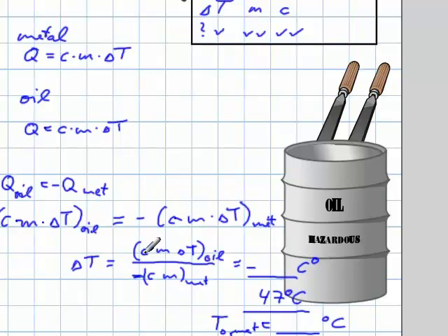This one is given in the problem as, what was that, 430 joules per kilogram Celsius degree. The mass here is 75 kilograms. The delta T here for the, oh, I'm sorry, hold on. This is for the oil here. So what I just said, 430 and 75, is down here, and then up here for the oil is 2700 and 710 kilograms, and then the delta T for the oil is 15 Celsius degrees. Everything is given. You come up with the numbers.